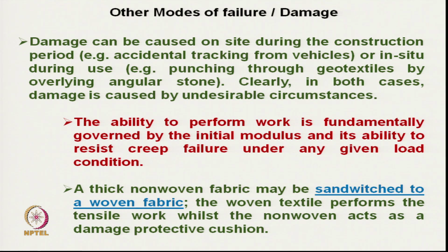So, this punching may take place, but this type of damages may occur and we have to design our geotextiles accordingly. The ability to perform work is fundamentally governed by the initial modulus and its ability to resist creep failure under any given load.